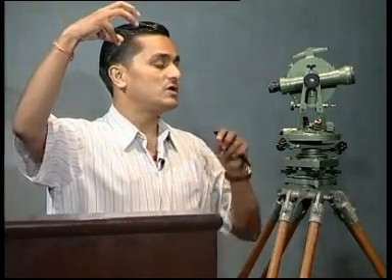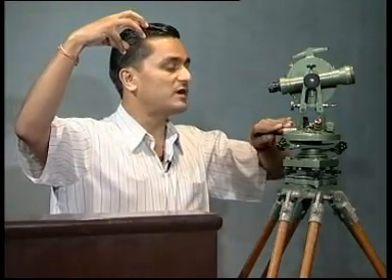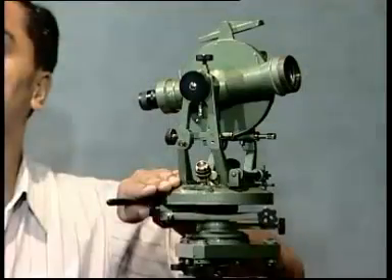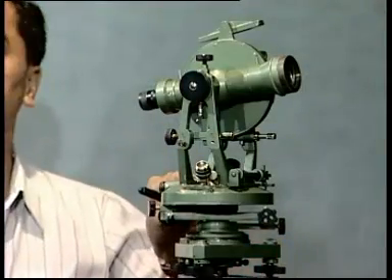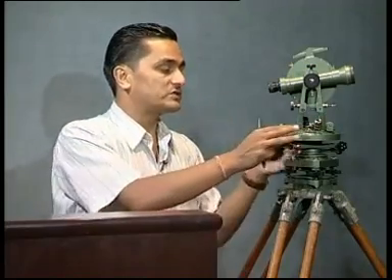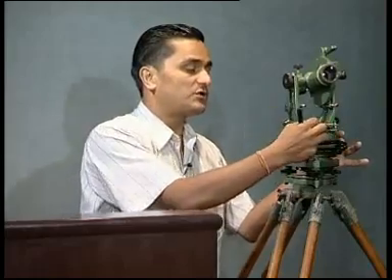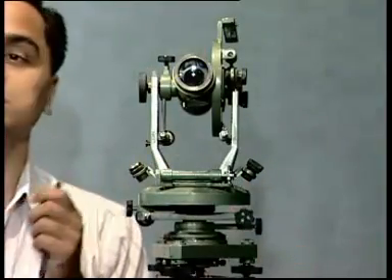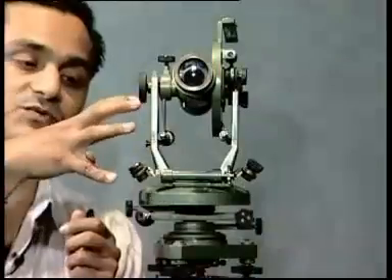One more error. For example, let's say the sun is on this side here. So only part of the instrument is being heated. Now if only part of the instrument is being heated, what might happen? The graduated circle may expand in one part, while it is not so in the other place. So again that might lead to some error. Also, that's my bubble tube here, and the sun is shining from here, the sunlight is falling on the instrument.